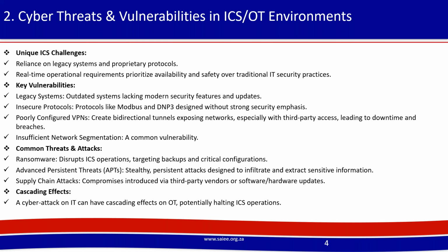Even remote access solutions, if poorly configured, can become significant vulnerabilities. Also, the jump servers or remote access servers where people securely connect to the business can themselves create unintended pathways for attacks. So the very same jump server that is there for something good can be used to bring down the plant if not done correctly. And also, inadequate network segmentation can leave systems exposed.